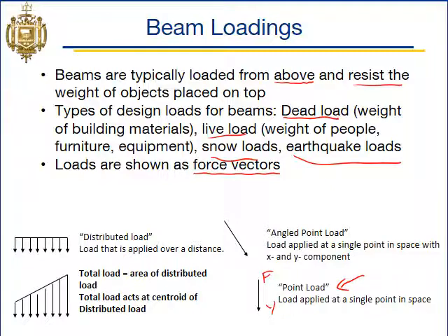That's kind of an easy one. We also have our angled point loads. This has an x and y component. You should already remember how to resolve that angled load into its x and y components. That's something you'll have to do when you do your analysis for the reaction forces.